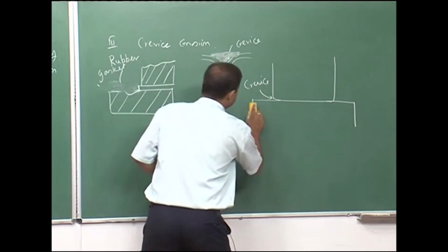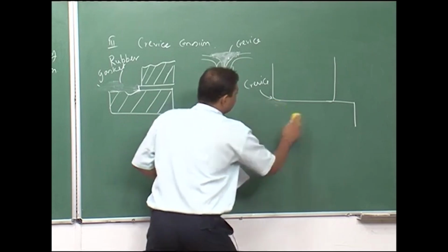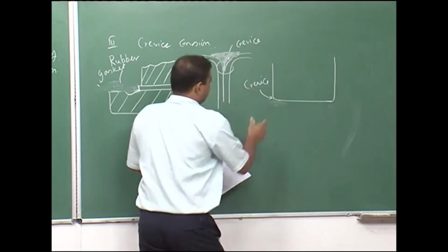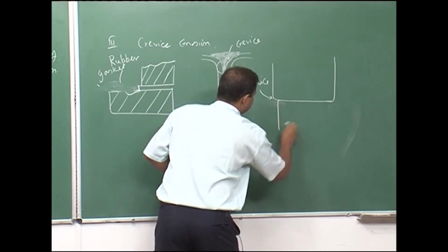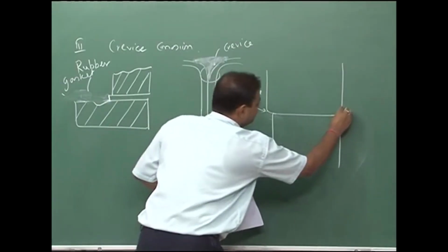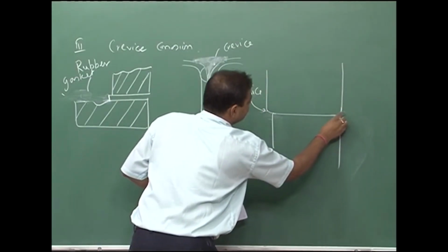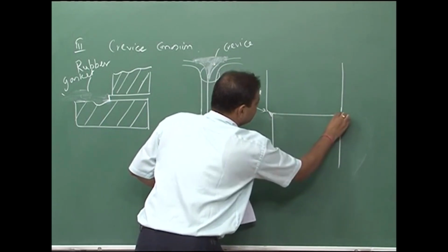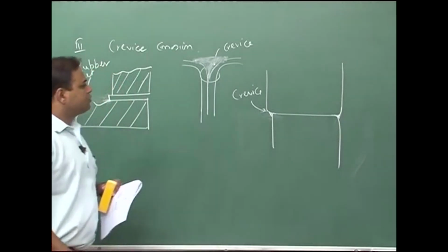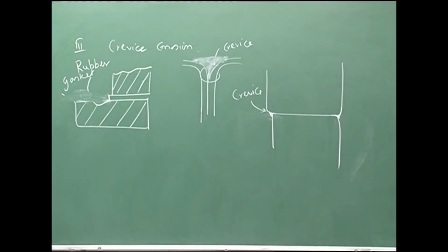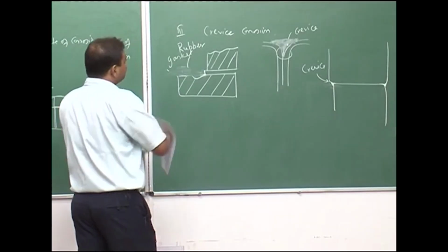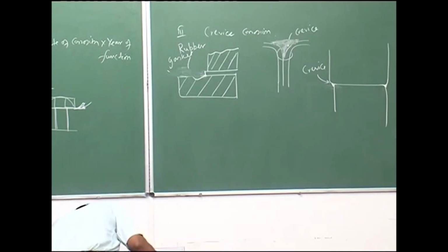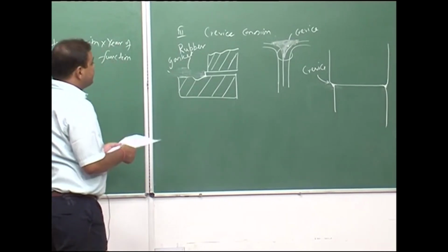So, instead of making the tank base this big, we can make the base like this, and here also we can put some material. So, by filling up this crevice part, crevice related corrosion can be avoided. This is crevice corrosion, which can be prevented by just changing the design.